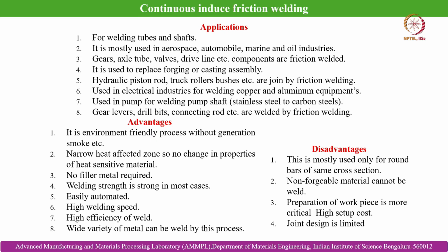And the disadvantages, as I told earlier, are the shape limitation of the workpieces that can be welded. It is mostly useful for round bars of similar cross section, and it demands much more preparation of the workpiece than other welding techniques, and that increases the recurring cost of the welding technique. It also deals with a high setup cost, and the joint design is limited.